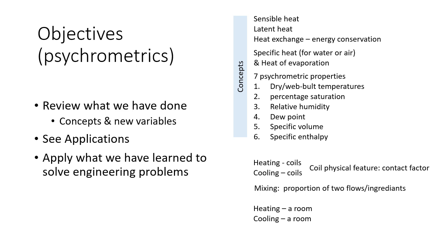So when we supply warm air into the room, we provide sensible heat to compensate for heat loss in the room to maintain a comfortable temperature in winter. Similarly, in summer, we supply lower temperature air into the room, allow it to rise, so the incoming air absorbs heat to avoid the room temperature rising. This is how we remove sensible heat.